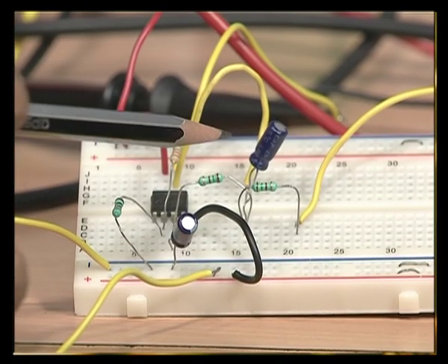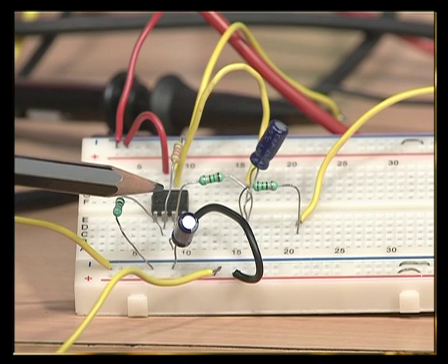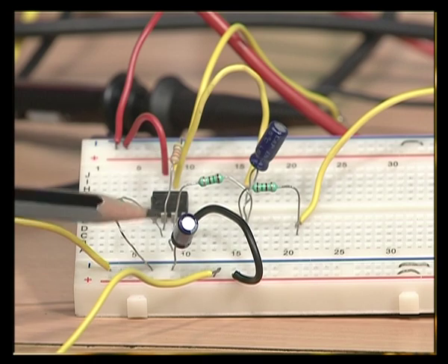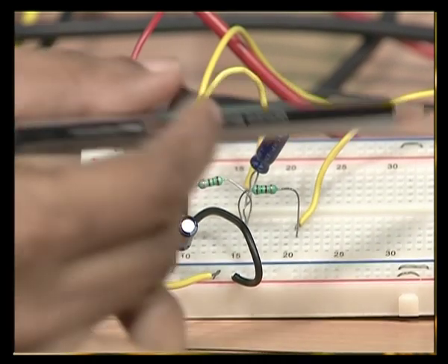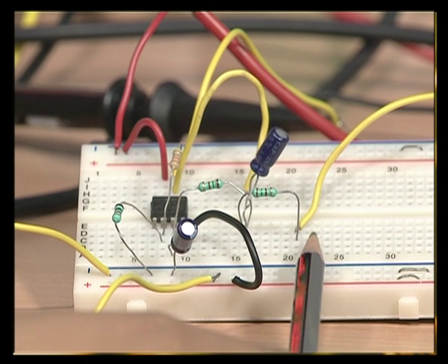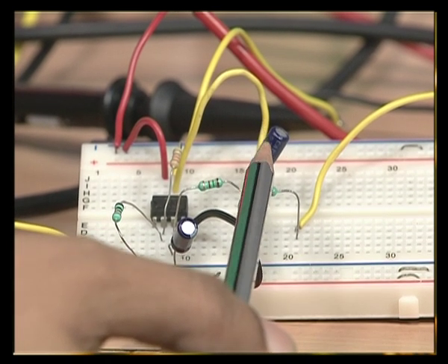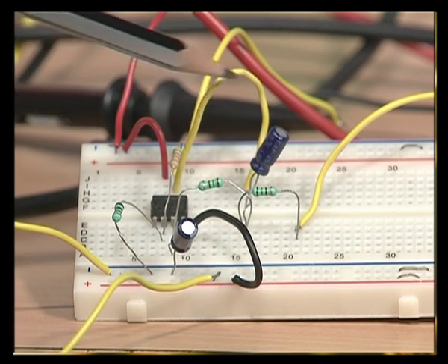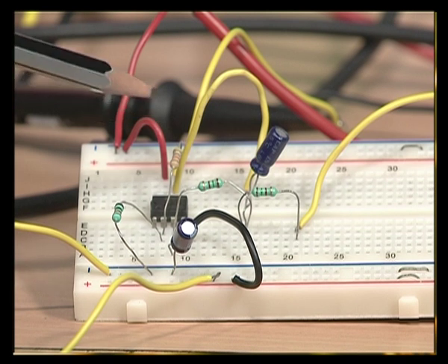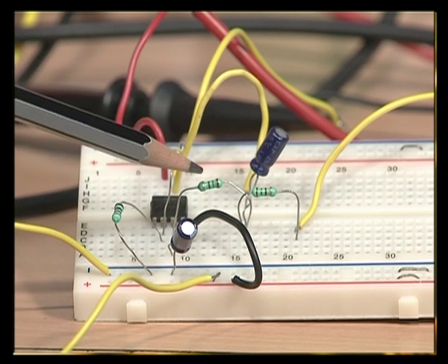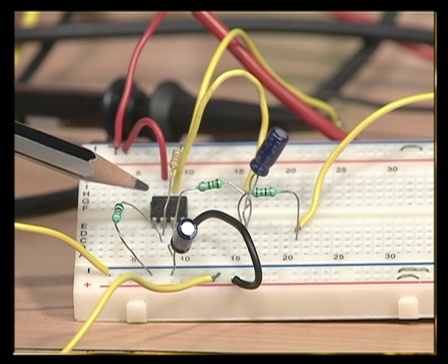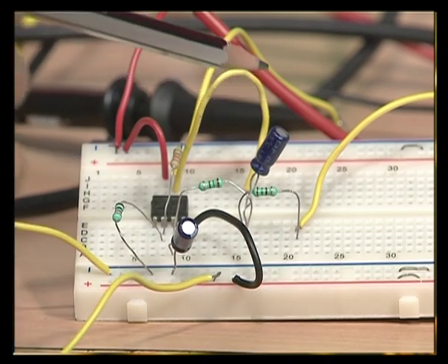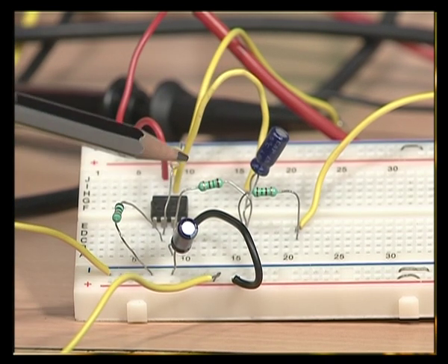The filter section here is two sections of RCs. You can see an RC here and then another RC here. To the first RC, the input signal is fed. To the resistor the input signal is fed, and the other end of the first capacitance is connected to the output terminal of the op amp. So, there is a feedback here which is required for the Butterworth configuration. In the second RC section, the R is connected to the positive terminal of the op amp, which is the third terminal, and then this capacitance is connected to the ground. These two RC sections constitute the low pass filter.